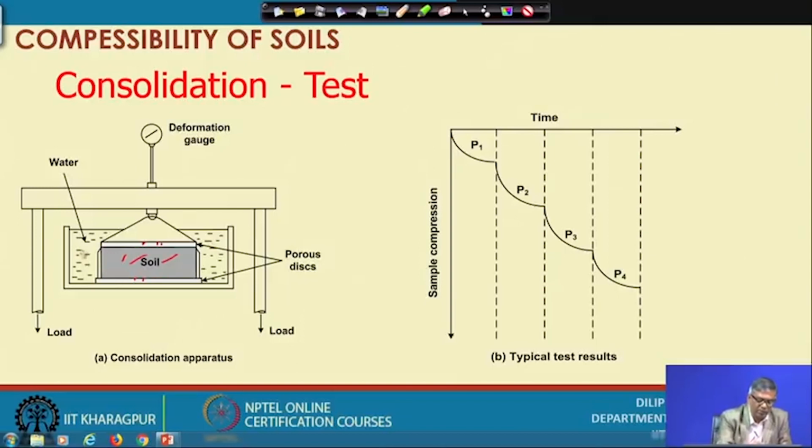The entire sample will be immersed in water so that it will be saturated, and then through this cover we apply the load. The load will finally be transferred to the soil through this mechanism. This is a saturated soil, and we have applied the load, and all the void spaces are filled with water.